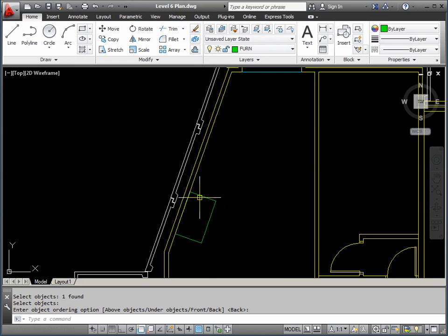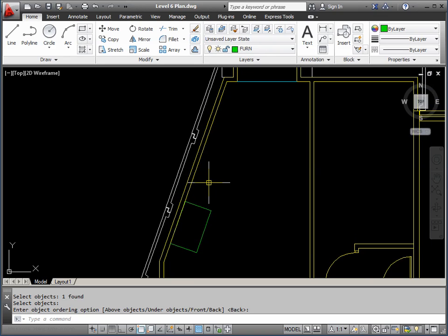Okay, that's a fairly basic way, and you'll get away with that for most things, but if you were doing a lot of work in line with this wall, then really you should change your alignment to the object. Okay, we don't rotate the plan. That would make things get out of control. What we do is we rotate our view in relation to the drawing. And we do this by changing the coordinate system.